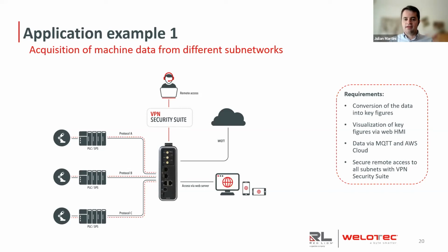concentrate the data on one device and then enhance the data, meaning doing some edge processing. For instance, perhaps compute the OEE or some other KPIs, and then visualize the data to make it visible to the machine operators or the decision makers. Visualize it on the web server, which can be accessed with any kind of device, which you see on the right-hand side, right? So it could be smartphone, tablet, PC, whatever. You can visualize the data.